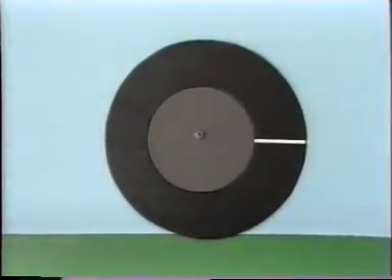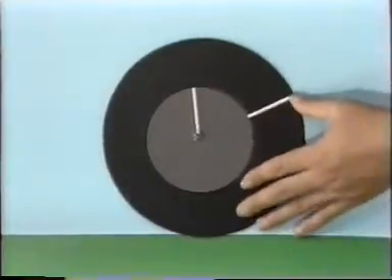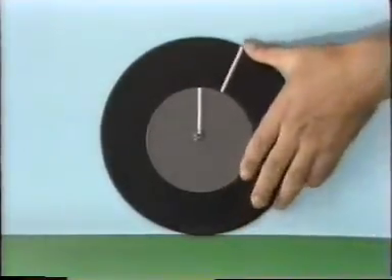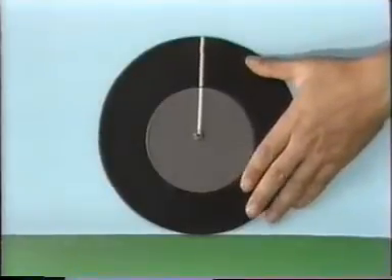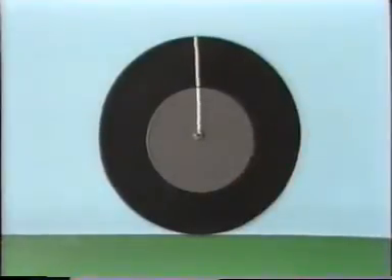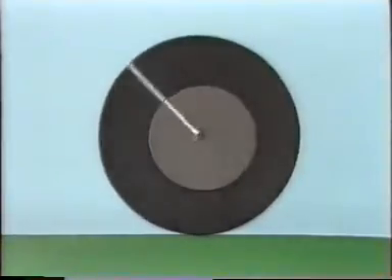In a case like this, the radial runout can be corrected by conducting phase matching between the tire and the wheel. If you move the thickest part of the tire to the point where the center of the wheel is closest to the rim, the radial runout will be reduced. This procedure is called phase matching. As you can see, the runout has been reduced.